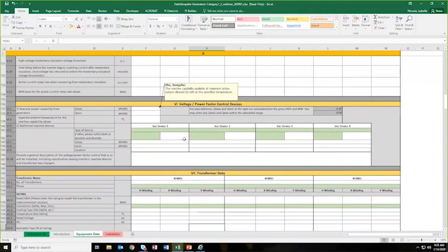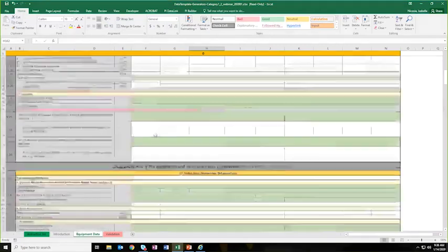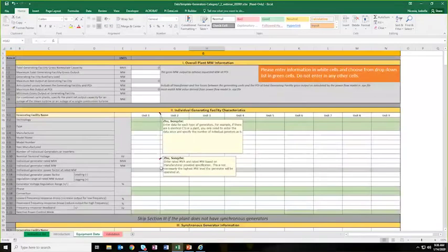Hello, this is Joey Zakowski of PG&E. I just had a couple of questions, and want to get a little more clarity on the expectation for the Qmax and Qmin entries and how they relate to the power factor regulation range up in the generator info section, I think sections I.14 and I.15. I think you mentioned when you were going through this that it was part of the generator specs or nameplate, and I'm having a little difficulty understanding where that number is going to come from, the individual generator power factor regulation range at rated megawatt output.